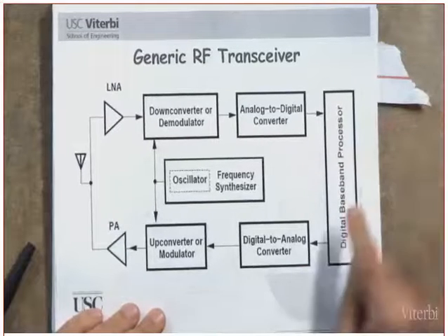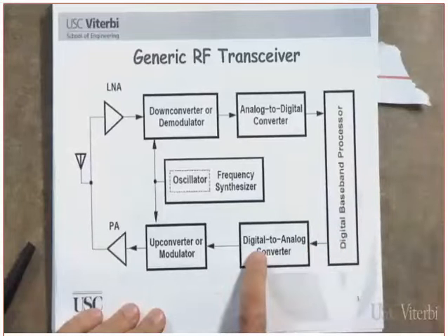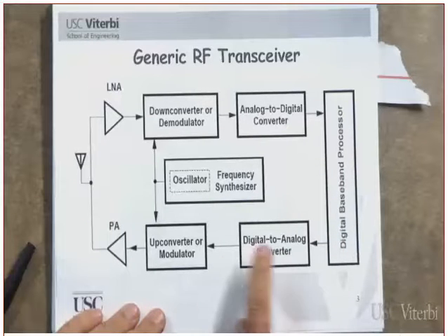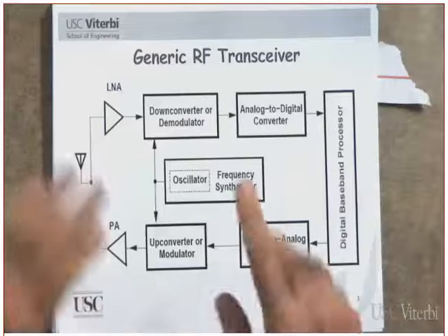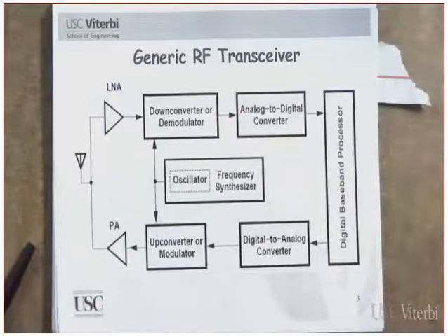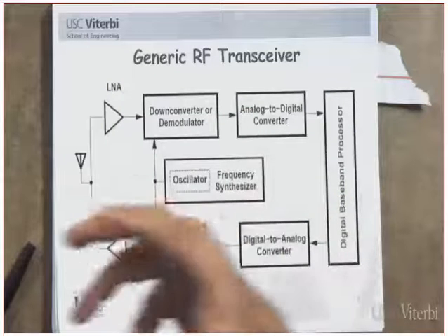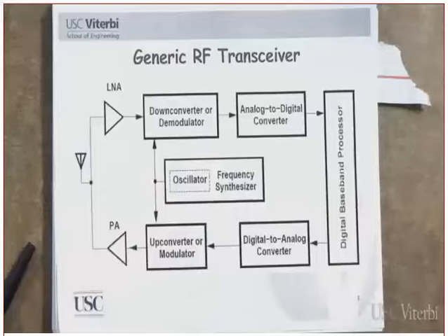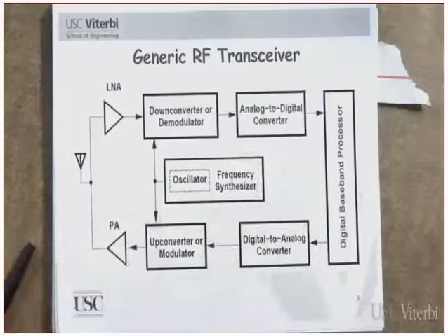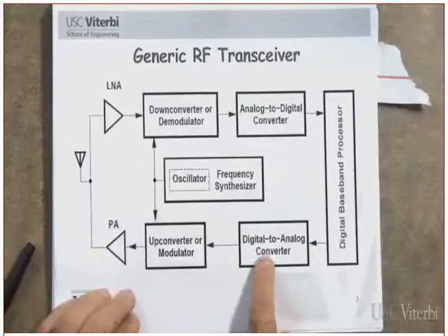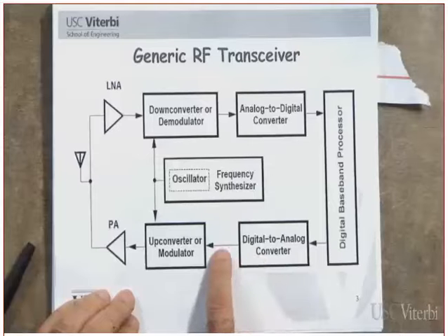So the processor here is generating a digital signal. This is a what? A DAC, converting it from a digital to an analog signal. And again, as I told you, for the purpose of what? Smoothing the edges so that the spectrum occupancy becomes what? Becomes more what? More compact, rather than keep getting that sinc function. Remember the sinc function? Instead of getting this sinc function, you try to what? You try to shape. Later on, by the way, we will also refer to this and the filter afterward. We call it what? Pulse shaping.